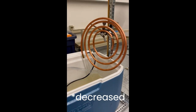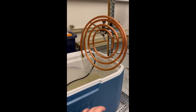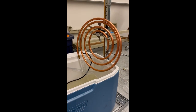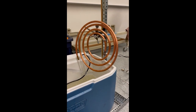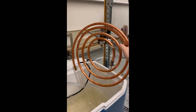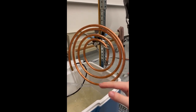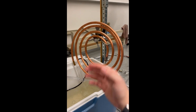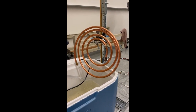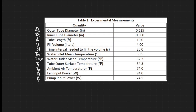So I'm going to now go into some theoretical backing for the things I just said, as well as some other reasons why we chose some of the factors that are in this pipe, and then how we can calculate all these things, including our convection coefficients, which determine how quickly heat transfers from the air to the outside surface of the pipe, then conduction from the thin pipe to the water, and then internal convection inside the fluid that is traveling through the pipes, which is our total heat transfer. So I'm going to go through the theoretical predictions for that and how we can calculate those things and analyze our overall performance of this air conditioner. All right, and we are back.